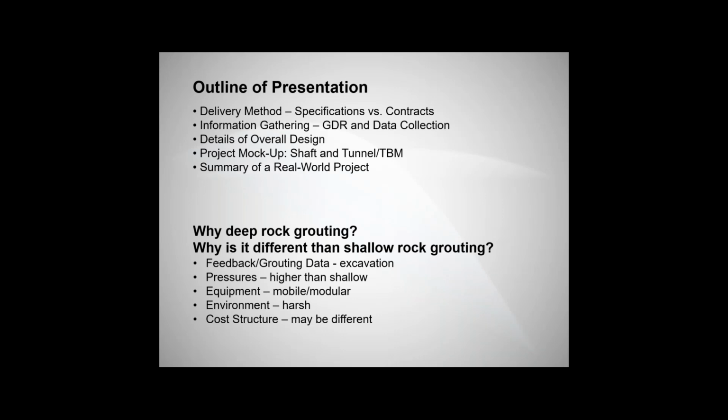One of the questions that may be in the back of your mind is, why deep rock grouting? How is that different than shallow rock grouting? Well, there's a lot of things that come into play. These are the key top 5. Your feedback and grouting data in your excavation is going to be different. Your pressures are going to be much higher than that of a shallow. Your equipment for delivery is going to be different, mobile versus modular. It's definitely a much harsher environment at depth, and your entire cost structure may be different as well. So those are some of the reasons why we've singled out deep rock grouting versus shallow rock grouting in this presentation.